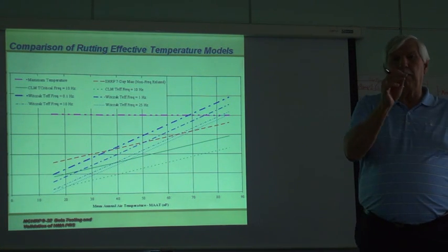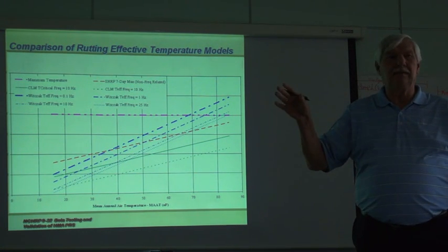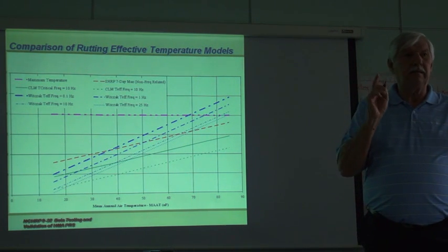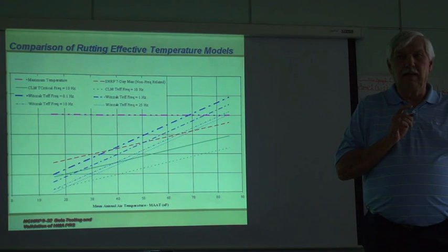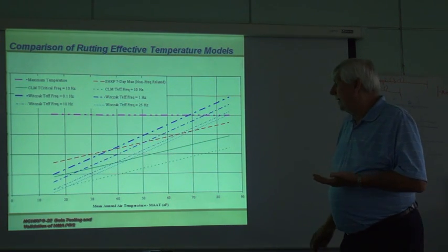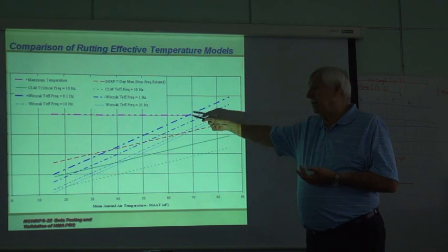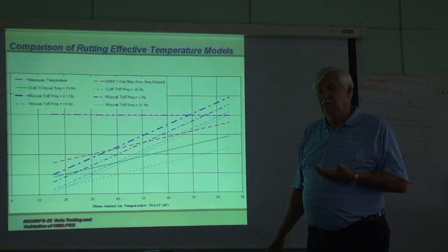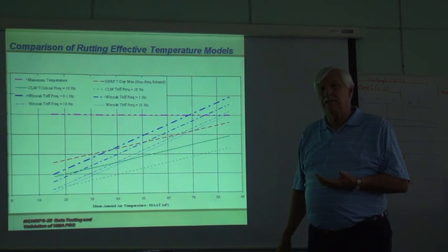And since Bruce Marshall's day to even today, states that use the Marshall test typically do it at 140 degrees Fahrenheit. So for all practical purposes, Canada uses a Marshall stability done at 140 degrees. Phoenix will use a Marshall stability at 140 degrees.